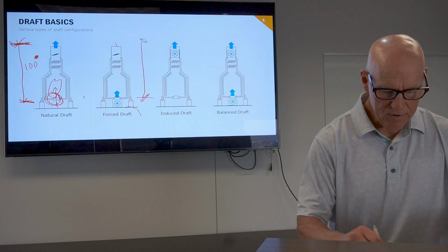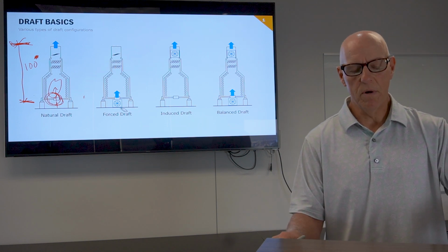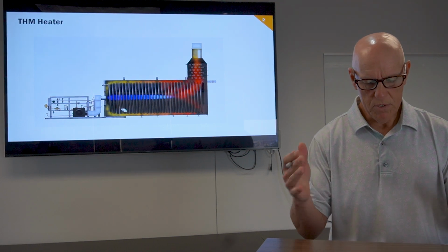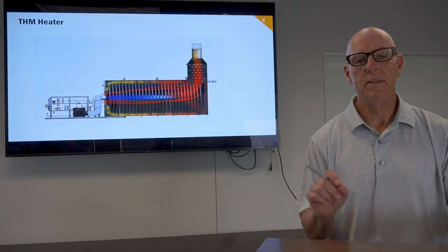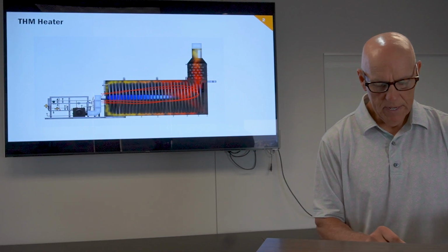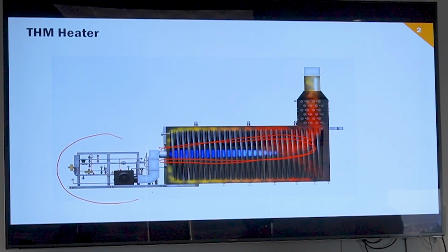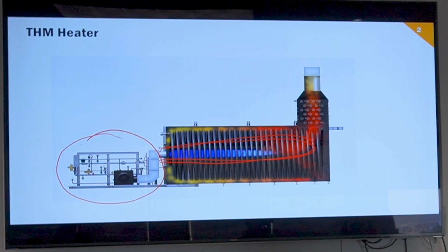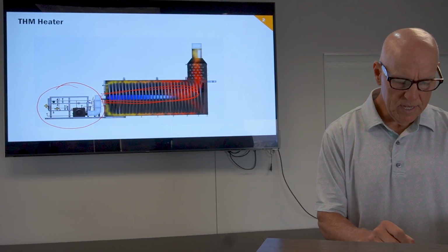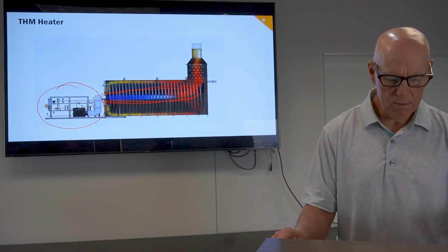There's another driver that comes with use of a blower. And let's look at what that looks like in something that we would supply. The other reason that I like a blower versus natural draft is you can see this system out here. This is the burner management system. This is what delivers fuel gas to the burner. And there's a lot of safety systems that are built into that burner management system that we've talked about before.